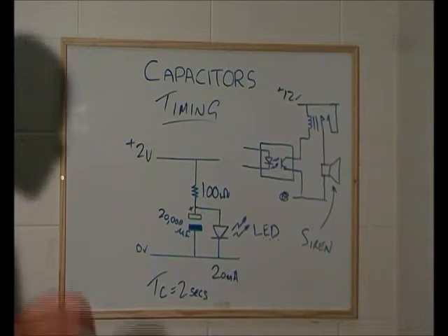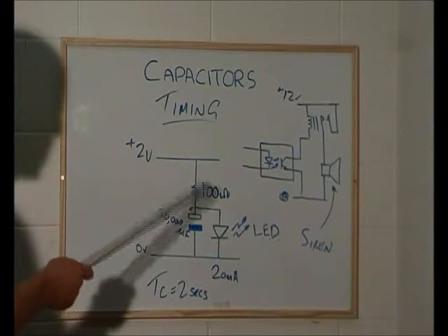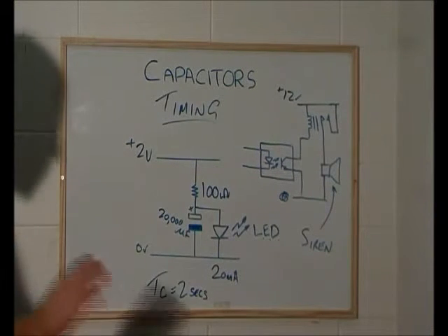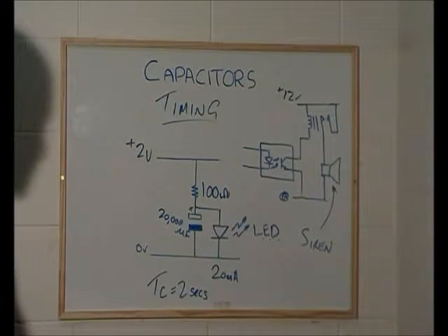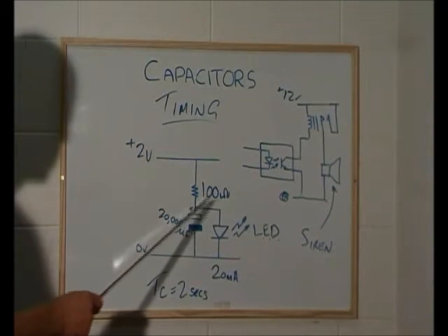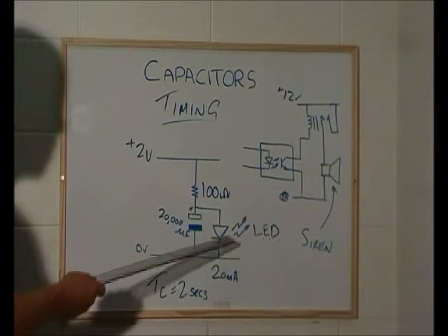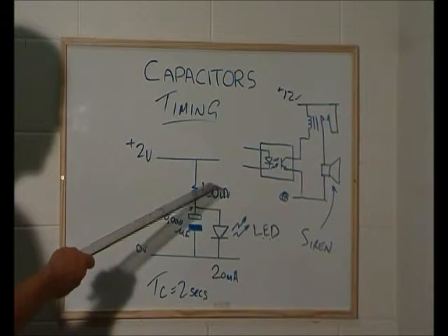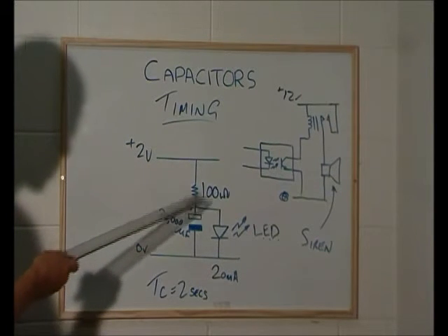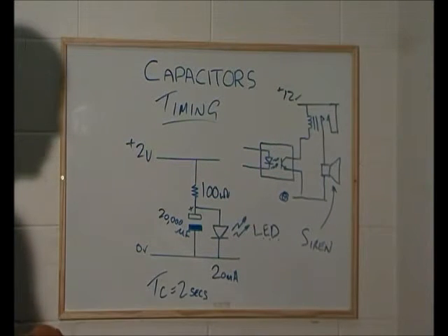It'll actually probably be a little bit less because we have to look at the resistance of the LED, because that is in series with the 100 ohm resistor. But in a perfect circuit where the LED had no resistance, we'd be limiting the current flow through the resistor to 20 milliamps via a 100 ohm resistor. But the LED will have a resistance, so this will drop down. The resistance of the LED plus R will equal 100 ohms total, limiting the current flow to 20 milliamps.